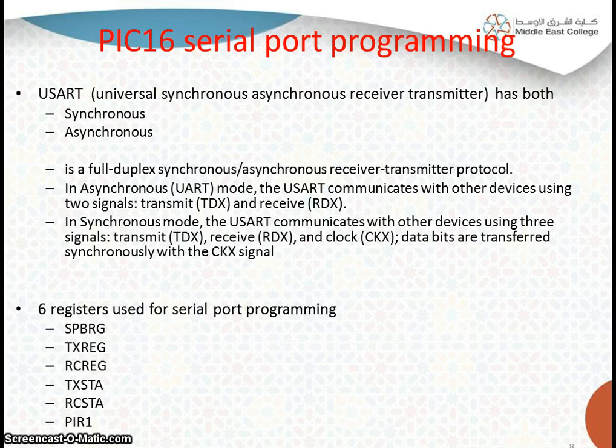They need not be synchronized between the transmitter and the receiver. But in the case of synchronous mode, along with the transmit and receive signals, the devices should share a clock also. The transmitter will be sending the clock as a separate signal along with the data bits which are to be transferred.